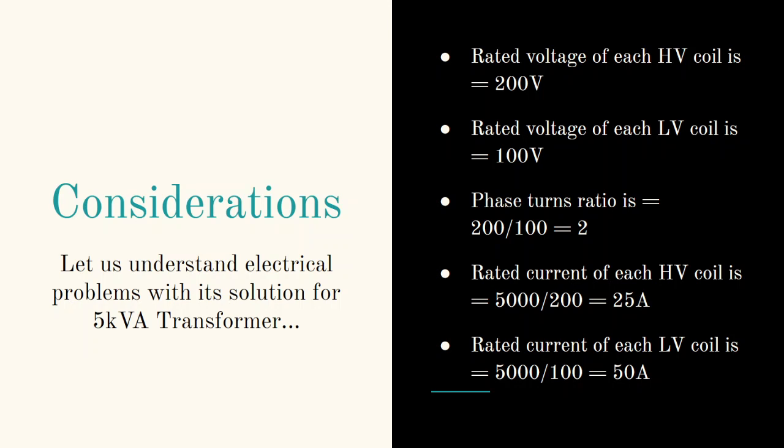In this case, we're going to consider a 5 kVA transformer. We talked about kVA, it's not kilowatt, it's kVA. The reason is it's a transformer, it does not have a definition of load, so it does not have a watt rating, since it does not have a power factor. So it's kVA. It can deliver about 5000 watts in theory, considering unity power factor.